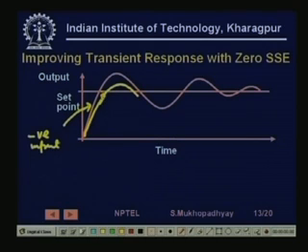As it comes closer, this negative input should increase. Similarly, around this point this negative input should also keep increasing so that it quickly turns, and then it will settle very fast. So you see it will not oscillate. We want that it does not oscillate so many times, but rather follows this yellow curve, maybe does a small overshoot and then immediately settles down. This is the kind of curve that we want.